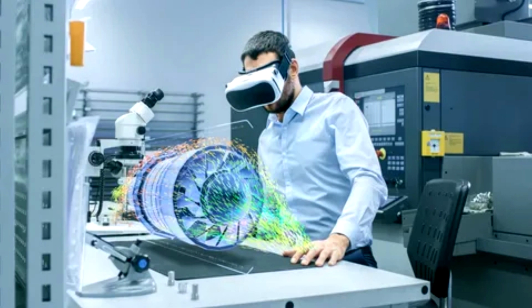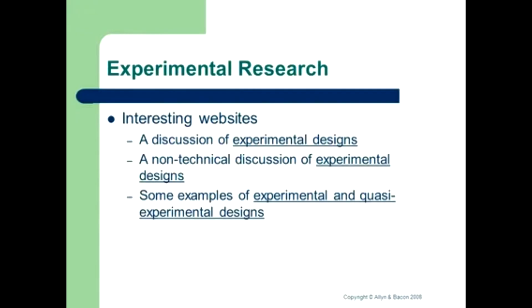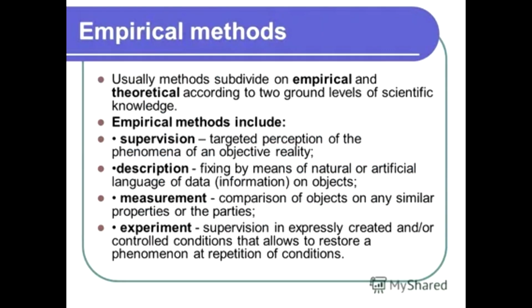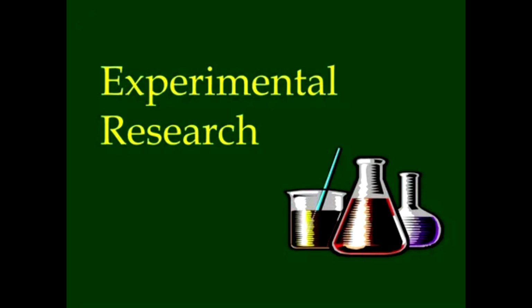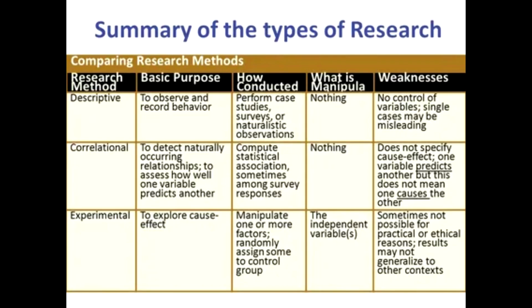However, scale models have other issues to be considered, such as boundary conditions and similitude. Similitude is the scaling effect of multiple variables such as dimensional, force, time, boundary and instrumentation. Fortunately, there exists established theoretical basis for scaling factors for various conditions. In a simple laboratory scale model for parametric study, only the dimensional similitude and boundary conditions are usually considered.